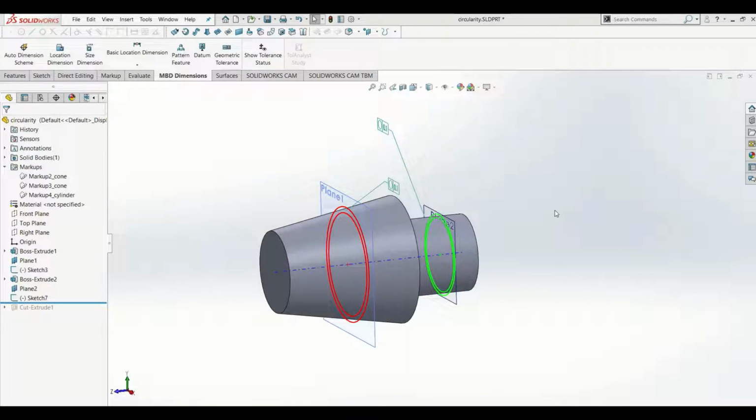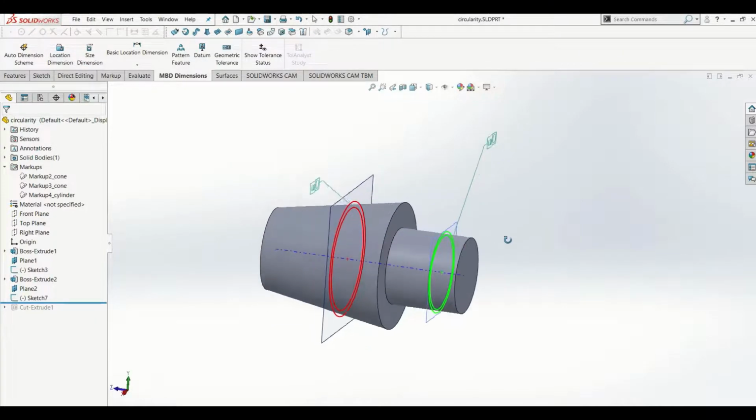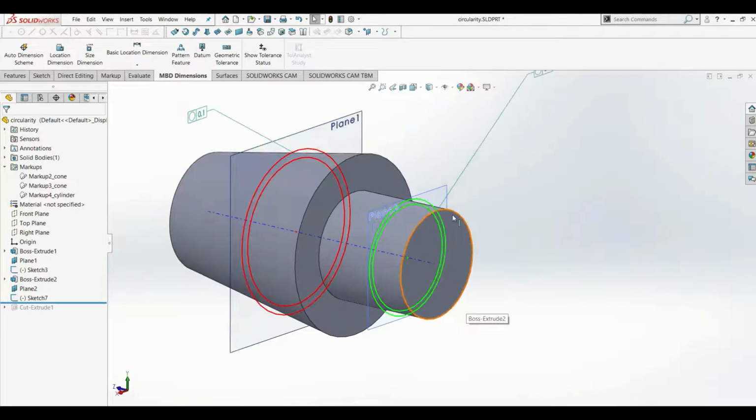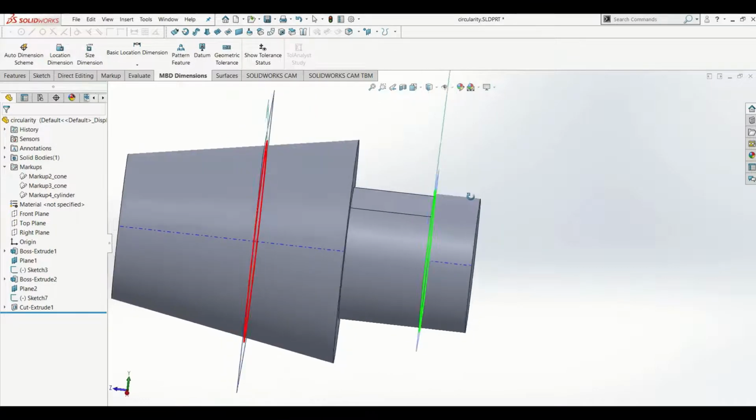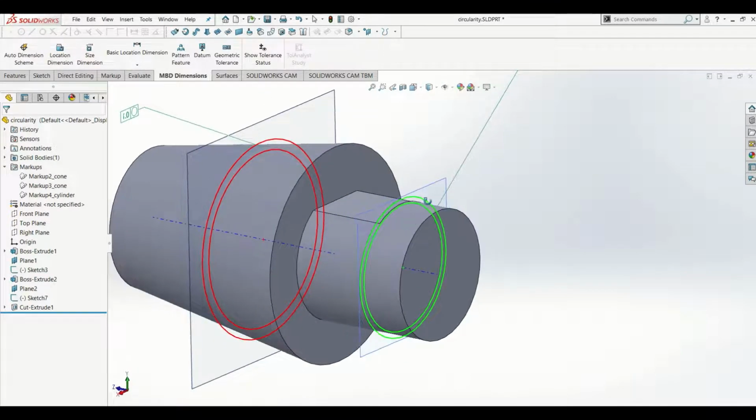Since the call is applied on one cross section, it might be a limitation of the roundness tolerance. In this cross section, maybe the true profile can fall within the tolerance zone, but it might not be possible for every single cross section along the length of the cylinder. For instance, certain portions of the cylinder might have a flat surface or uneven surface.